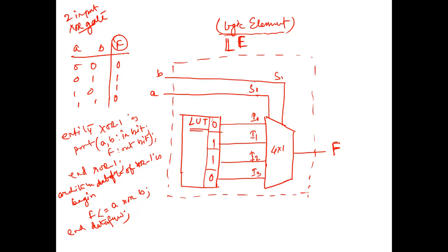Now, what actually happens inside the FPGA kit, the FPGA board? This is absolutely a research topic. This class is for MTech, so that's why I'm discussing in depth how it actually works. When you are downloading, that means there is a lookup table, an SRAM based lookup table, present.